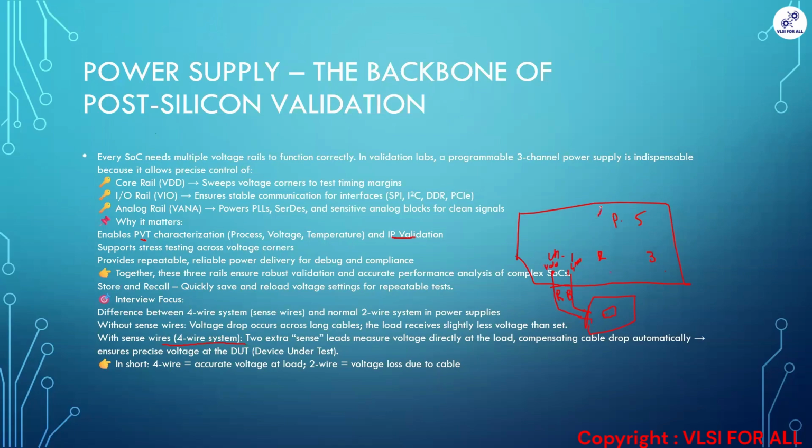At the back of this power supply, we'll be having another 2 wires, which are sense wires. So, we'll connect that sense wire. We need an accurate voltage at the load.